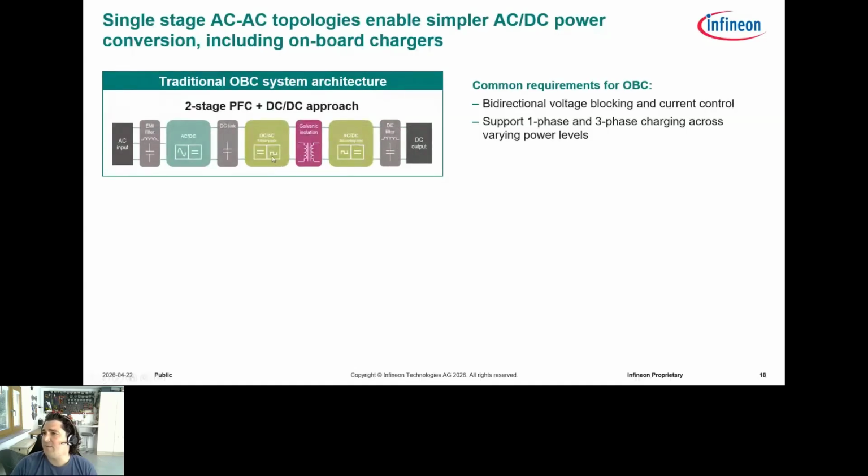When we talk about AC to AC topologies or single stage topologies, we're talking about replacing this part here. And as I mentioned, you have a very large DC link in the middle. It's very desirable to get rid of that. It's bulky, it's expensive. Electrolytic caps are notorious for having short lifetimes. A lot of people are moving towards hybrid polymer caps for that reason, which are a lot more expensive.